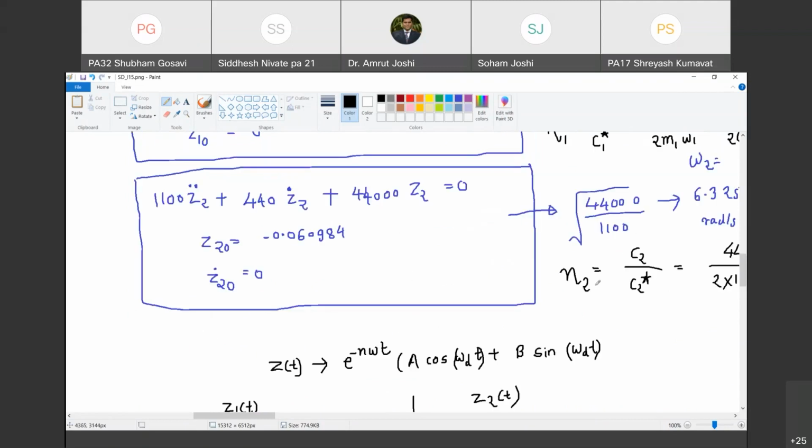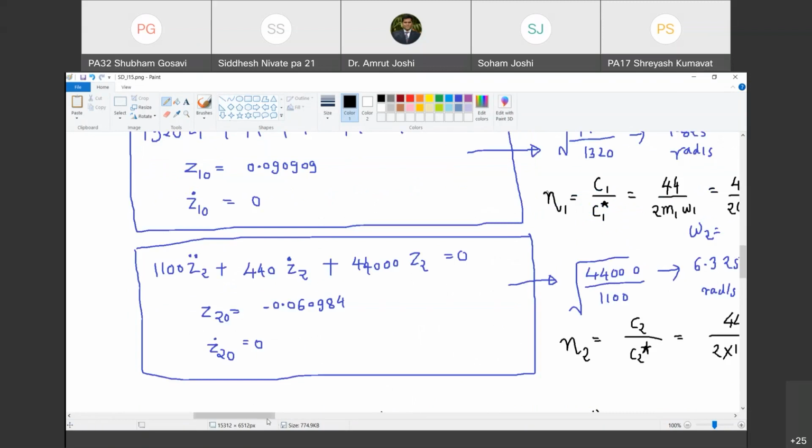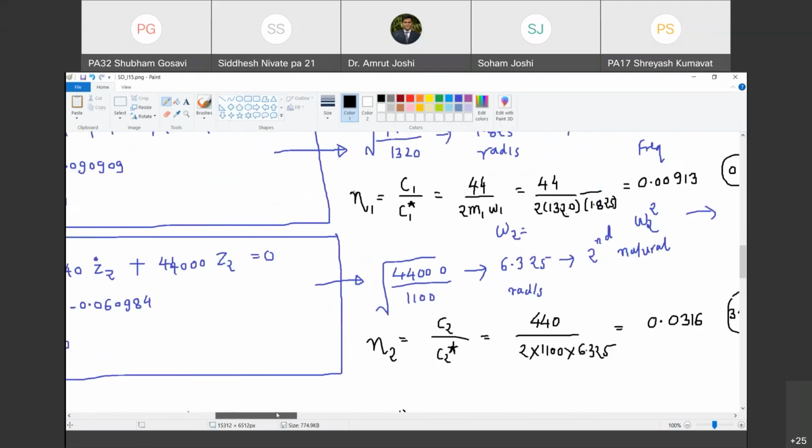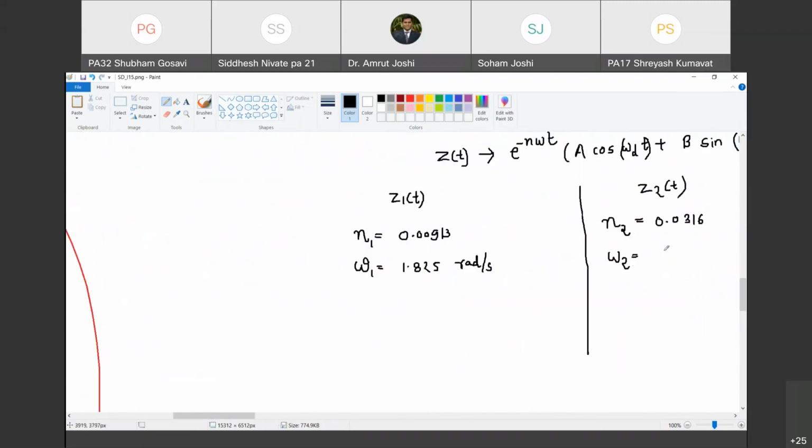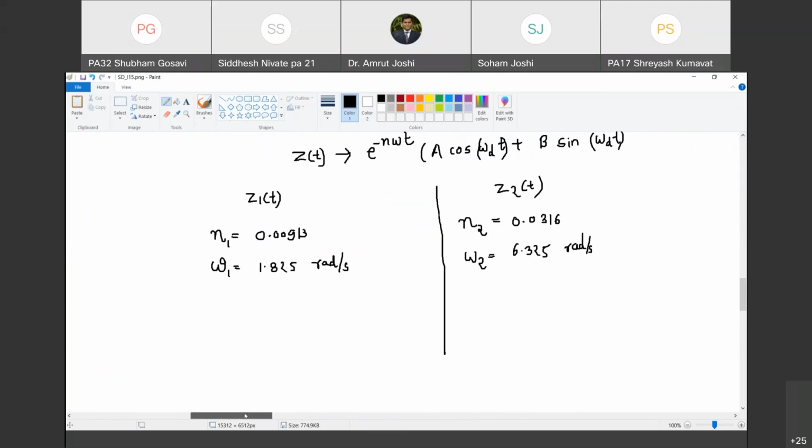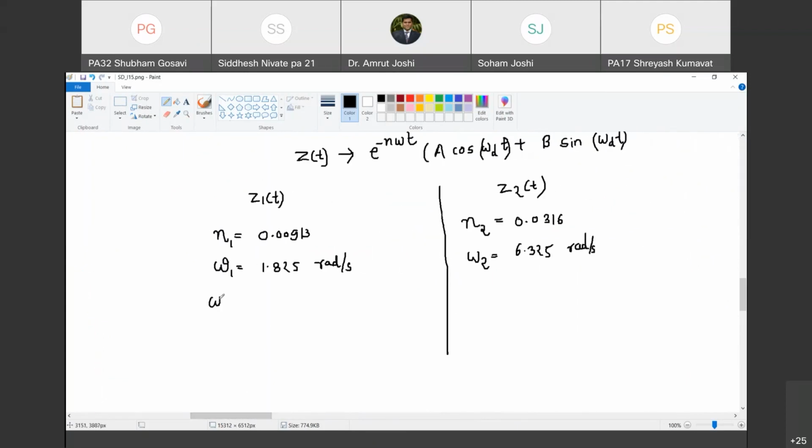So what is the second natural frequency of this system? Omega 2 is equal to 6.325. Are you with me? You have to also understand that these frequencies are in radian per second and are not in hertz. Are you with me? Yes, sir.